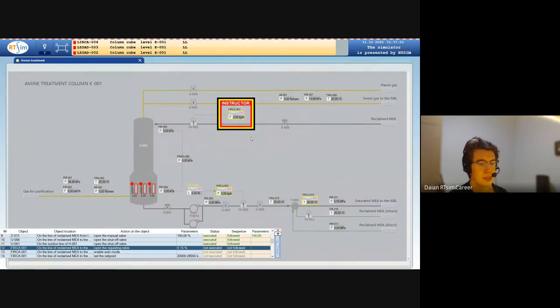shadow valves, and now we move on to point 12, the flow rate device of regenerated monoethylamine, and we are starting to fill our absorption column with the regenerated monoethylamine little by little. There is already raw material in the section of pipe, and now we will gradually open the regulation in order to check the regulator opening operation. The PV1 control valve is controlled by the FIRC1 device.